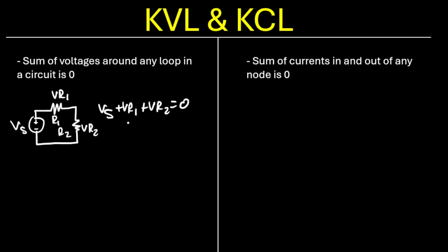resistor. Now, one key thing you need to understand is why the voltage drops across the resistors are negative and why the voltage supplied by the voltage source is positive. So, think of these resistors like hills, where the top of the hill is the positive or the higher potential terminal, and the bottom of the hill is the negative terminal or the lower potential terminal. And think of the conventional current flowing through the resistor as a boulder. So the boulder starts at the top of the hill and rolls all the way down to the bottom.